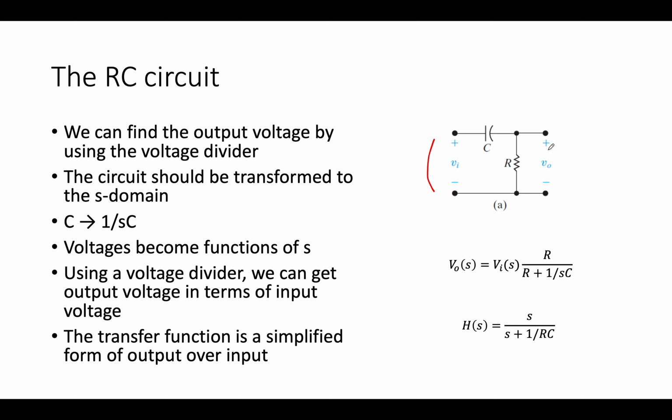As you calculate different transfer functions for this particular circuit, you could see there would be two possibilities. One would be to take the output voltage over the resistor. The other would be to take the output voltage across the capacitor. The transfer function will change, but as you'll see, the poles, the denominator of the transfer function, will not change, and the poles will remain the same.